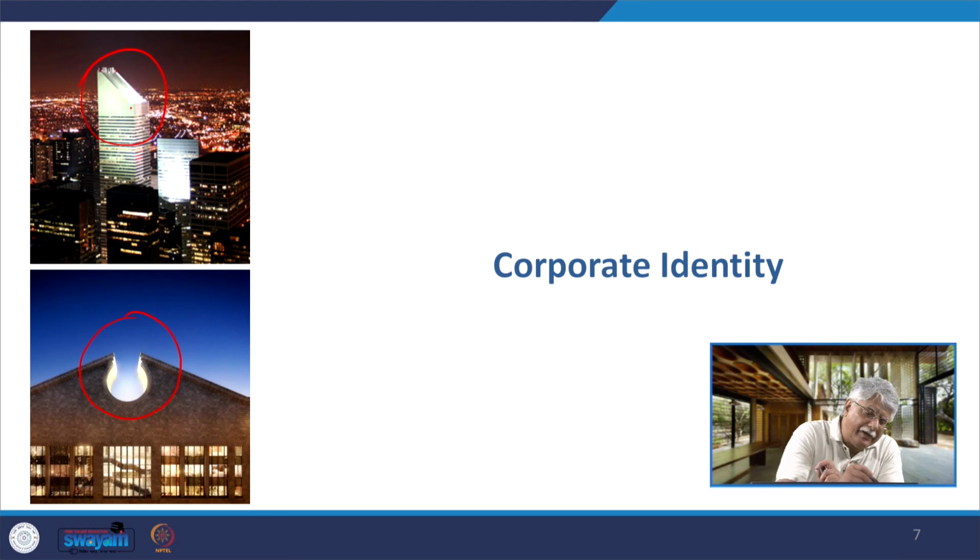One of the reasons why Citicorp Center had this pinnacle also is because it has a TMD, a tuned mass damper, that has been provided right at the top of the building, to prevent lateral sway that happens because of either wind loading or in the case of a seismic event.